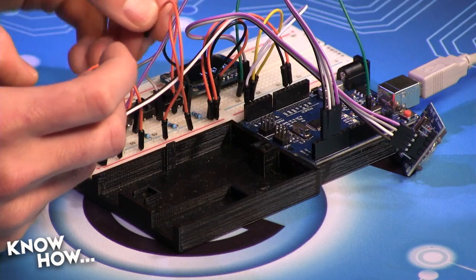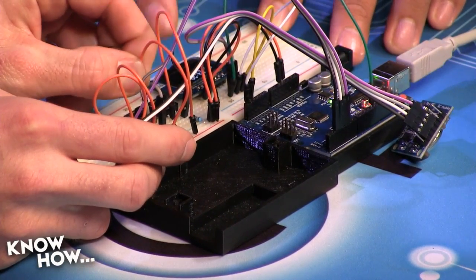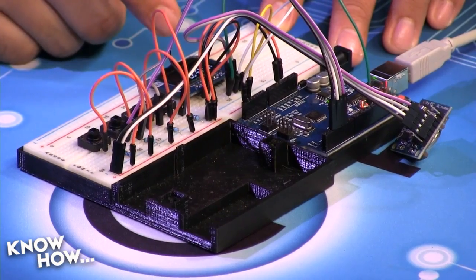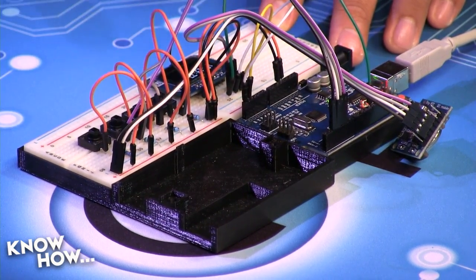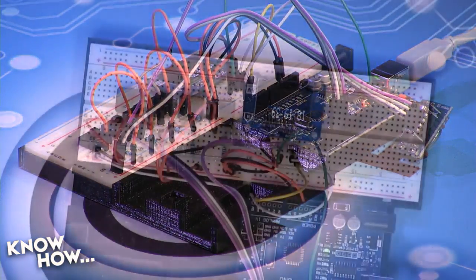And remember, the reason we're doing it this way with that pull-up resistor is that in normal operation, when the switch is not pressed, there is a very, very slight current flowing through that 10K resistor. When I push the button, it actually shorts it. It goes directly from the ground rail into my digital pin. So I have low current normally and then high current when I push the button. Off or on. That's what we're using to set off or on.